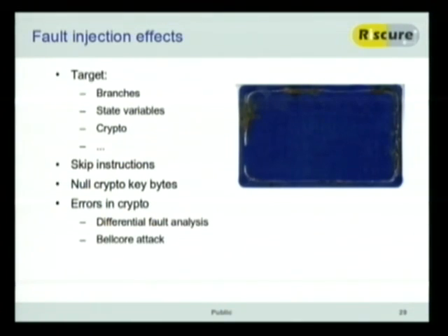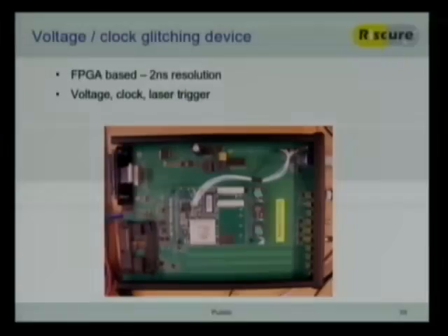There's actually one attack that if you have an RSA Chinese remainder theorem implementation, you can actually glitch it once and once do a normal execution, and just from the difference of those two you can recover the entire key, which is pretty strong, you could say. Now if you really want to kill your target, that's not too visible, there's actually somebody who tried to do fault injection using a microwave oven. That was more of a permanent glitch.